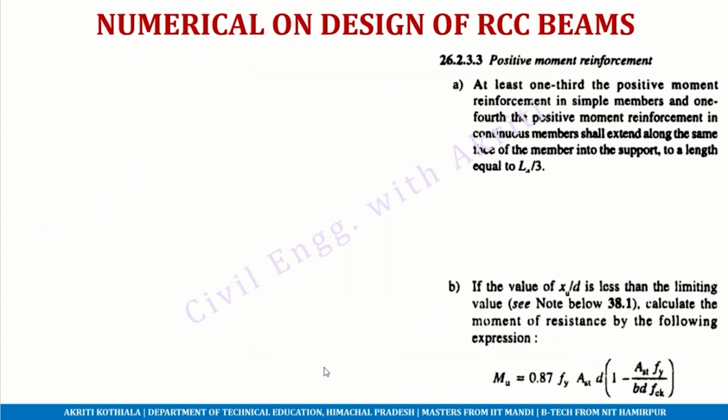Up till here the question was exactly same as what we had done in the third lecture of the series, RCC 1C. Therefore I have rushed it and I have revised it quickly. Now, after this stage in the previous question we had designed vertical stirrups for the beam. However, in this question, we'll be looking at our option of bent up bars as well. So from here, we'll be solving this question.